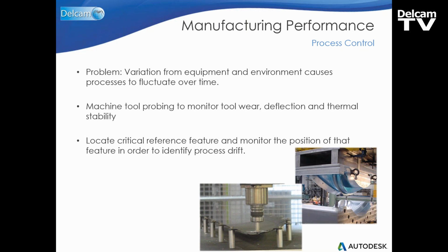We can then insert the logic into the NC code that it performs the tool change, that it probes that bore, and then uses the results and says in the code, is that feature in tolerance? Yes, no. If it is in tolerance, then we can go on to machine bore number 2, then change again, probe change, bring the probe in, is it in tolerance? Yes or no. If it's not in tolerance, then we can say, okay, we need to do some more machining.